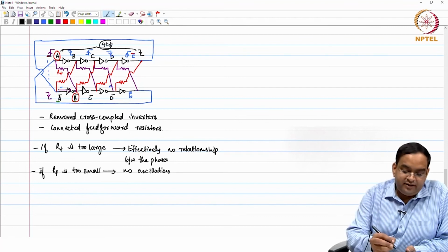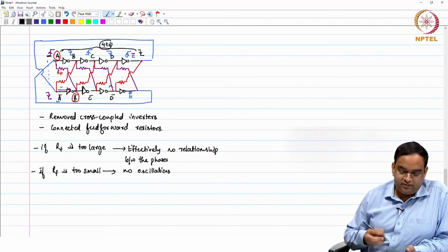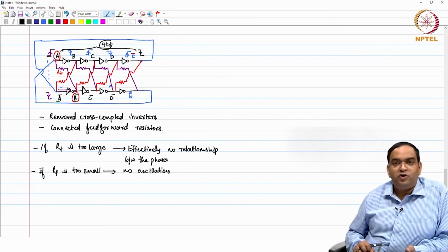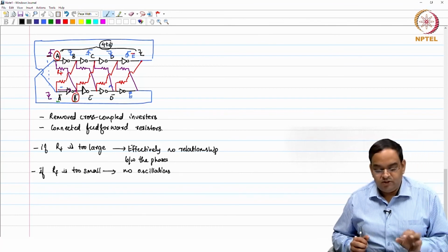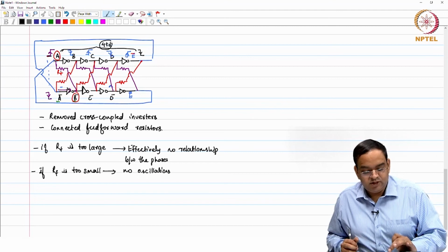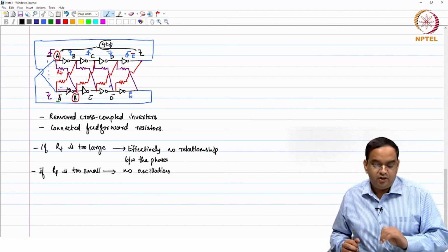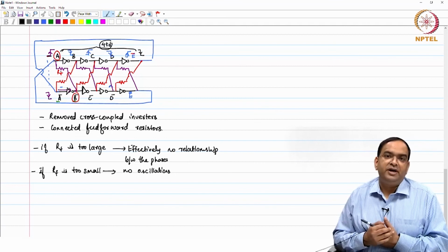An important thing here is that as soon as you use the resistor, you are loading your output nodes also, okay. So, it increases the parasitic capacitors and other things, then the frequency will be lesser, okay. So, you have to try to minimize the parasitic capacitance which is coming whenever you add anything to this circuit.